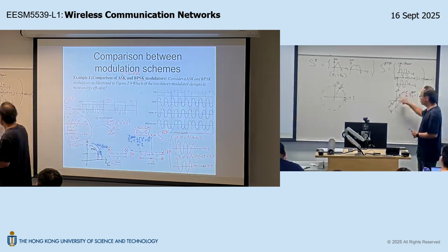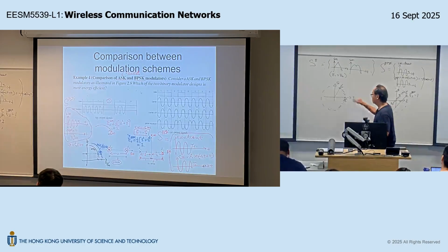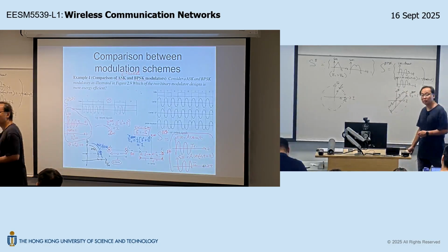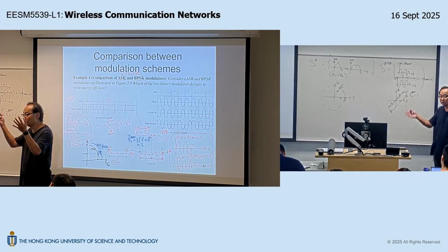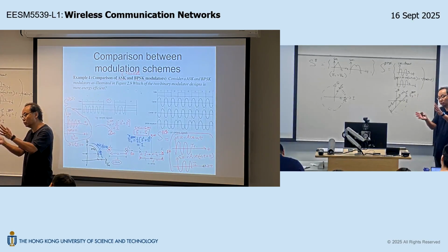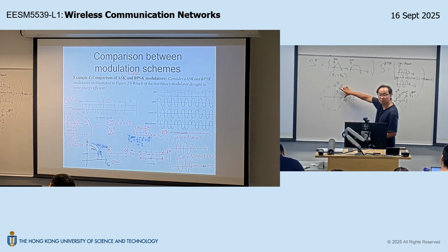So it's a unit circle, right? So for this one to achieve the same energy, this is also a unit circle, 1 unit here, right? Then the resulting error probability is determined by what? Overlapping area, right, as always. And overlapping area depends on what? Depends on the separation of the centers of the two noise clouds. That is the separation of these 2 points, right?